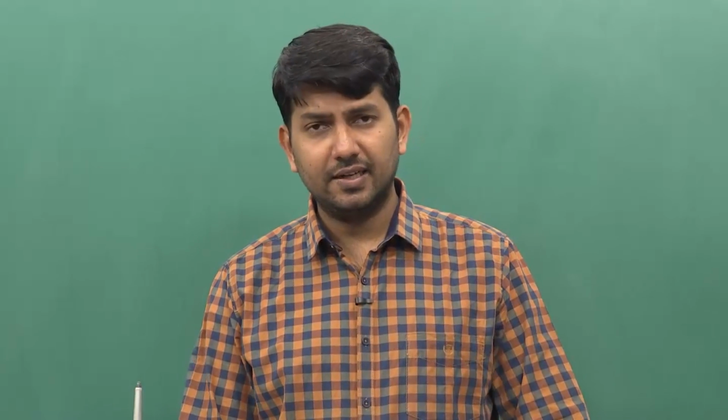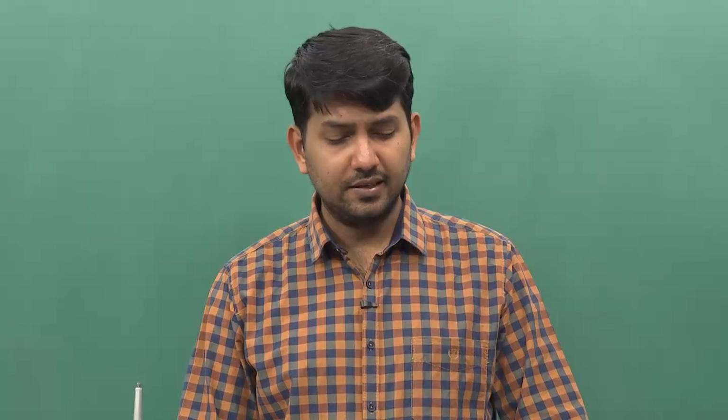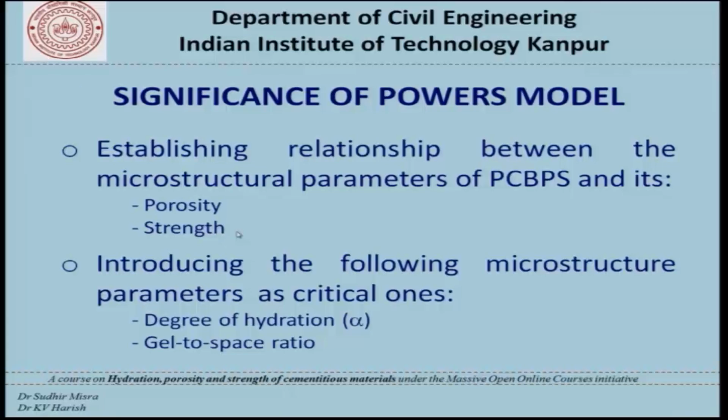Remember, in the macro level strategies that we discussed under mix design strategies, strength is a very important performance parameter like workability and durability, and we typically do not know how to correlate strength and porosity from those strategies. So, the microstructural parameters in Portland cement based space systems are identified in Powers model, and efforts are taken to correlate those factors with porosity and strength. That is the special thing in Powers model.